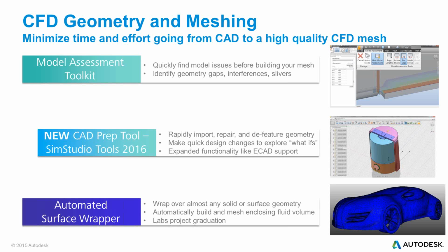One thing we're also doing is starting with surface wrapping. Everybody was on labs this summer and noticed that there was a lab project called Project Ventus. Its purpose is for external aero type of models, where you can put an external boundary volume around any model, come from anywhere. It can come from surface models, SketchUps, even CAD types we don't actually support inside of Autodesk CFD. It'll surface wrap that model, build a mesh that's CFD compatible, and then you can import that mesh into CFD. So we included that application in CFD 2016 as well.